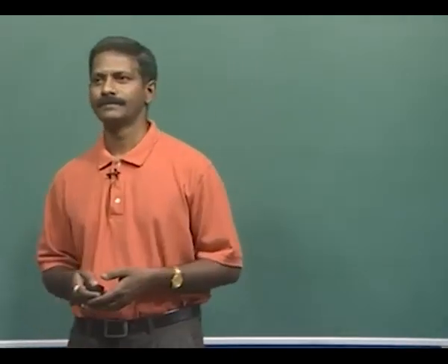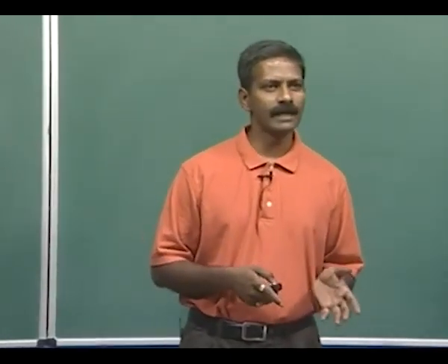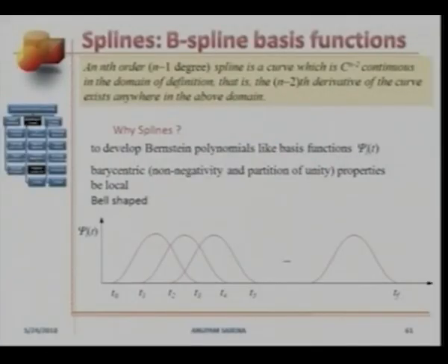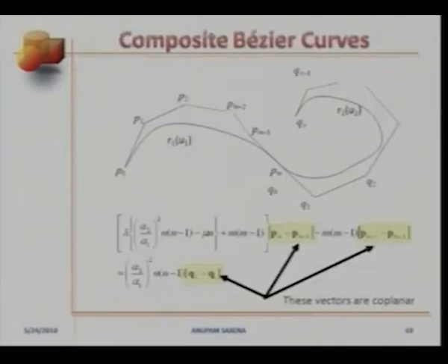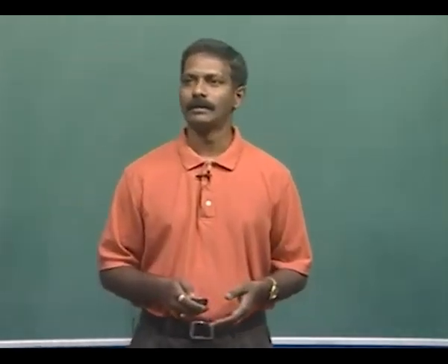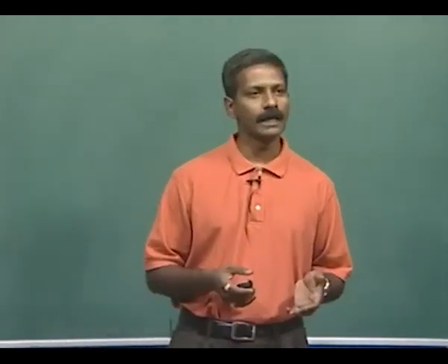Now, splines. Let me go back one slide and try to motivate why we started studying splines. Let's take a look at one Bezier segment. If I move any data point, the shape of the entire Bezier segment would change. Not of the composite Bezier curve, but of the Bezier segment. We did not want this to happen. We wanted to impart local shape control properties to our curve model, and that's why we went on to studying splines.